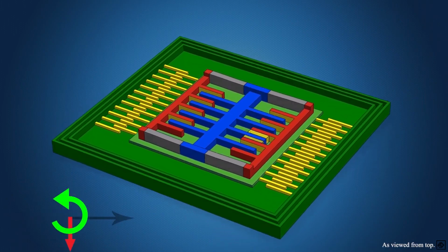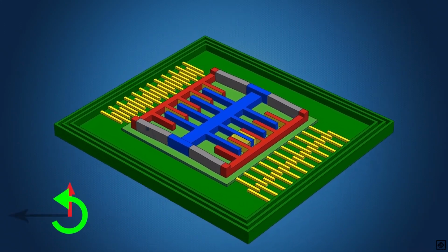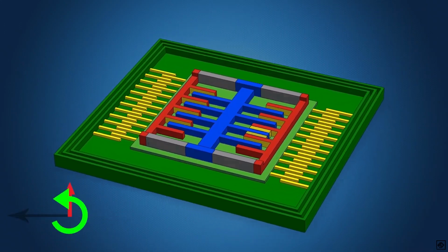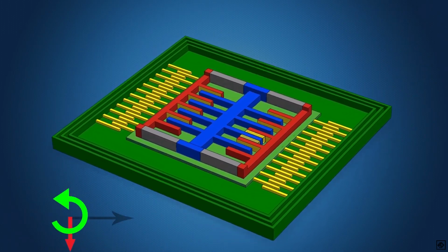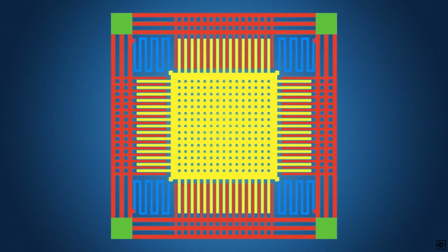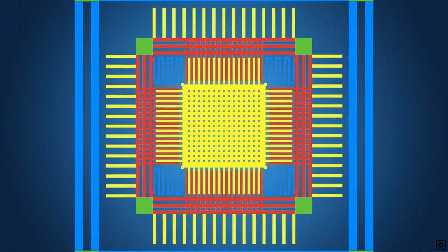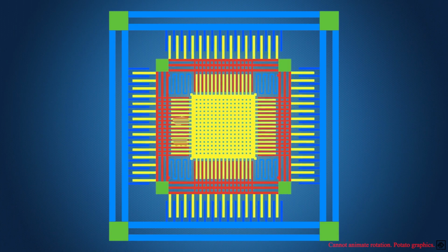This accelerometer can detect acceleration in 2 directions, and so can the gyroscope. Both the rotations are perpendicular to the linear motion of the accelerometer. Rotations in the axis parallel to the motion axis will not show the Coriolis effect. To scale this to the third direction, we oscillate a 3-axis accelerometer in 2 directions, or in a plane. Its microstructure looks like this. This can detect rotations in all 3 directions. So using the gyroscope, the phone can detect how much it has rotated over which axis and process that.